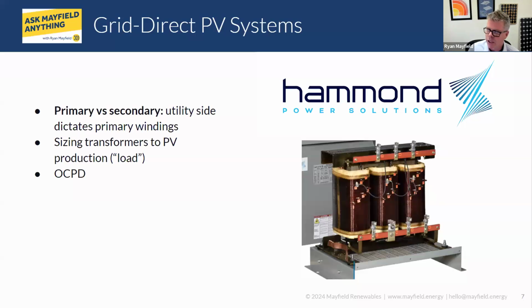Perfect. And then a question that came up was around oversizing for harmonics. Is that something that's necessary, Nick? Usually when harmonics come into play, that's around when we get the bigger inverters. It's not exactly oversizing, but we'll often put a K factor on the transformer, like a K factor 4 or 13, to be able to withstand those harmonics. But in principle, yes, it basically is oversizing the transformer to withstand the harmonics, which we usually just address by a K factor on the transformer.